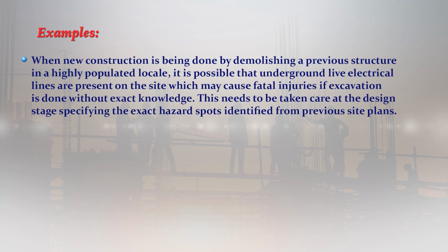Examples: when new construction is being done by demolishing a previous structure in a highly populated area, it is possible that underground live electrical lines are present on the site, which may cause fatal injuries if excavation is done without exact knowledge. So this needs to be taken care of at the design stage, specifying the exact hazard spots identified from previous site plans. So that can be done at the design stage.